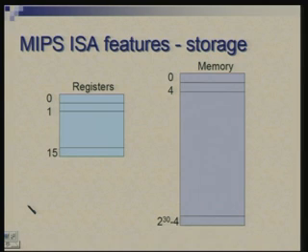The storage structure is shown here. You have 32 registers. As far as instructions are concerned, almost all instructions can use any register with equal ease. So, you have registers numbered from 0 to 31, which requires a 5-bit field to access them, and wherever there is a register field, you can put any register. Although we have seen that there are cases where some registers play a specific role.